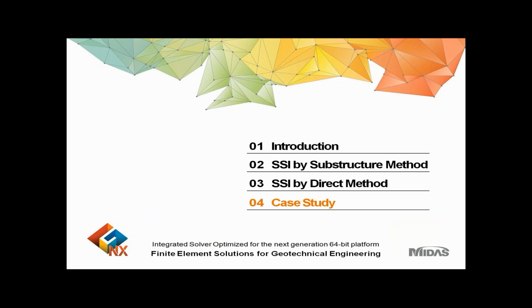From the geotechnical viewpoint, the results of settlements, total and differential, the distribution of loads and bending moments in the piles, the interaction between the raft and the soil, which is the Piled-Raft hypothesis, and the interaction between the piles, which is the group effect, are very important topics that can only be achieved with some accuracy when using 3D numerical modeling. So along with a platform that enables this modeling, the soil properties might be modeled with the use of soil constitutive models, and MIDAS GTS NX allows this analysis to be done with all those prerequisites.